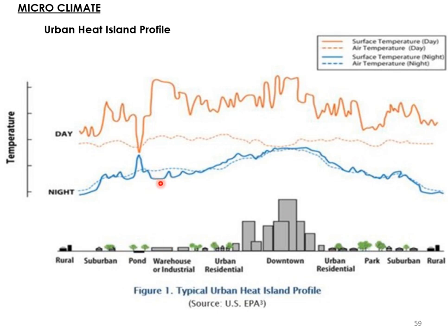Whereas the surface temperature will suddenly reduce here in a warehouse, because sometimes what happens in a warehouse, it's a very thin material. So the thin material can re-radiate faster. So that is why it is making the surface temperature a little lesser after your work hours. Like after the work is completed by 5 o'clock or 6 o'clock, and it's left very idle and nobody is there in warehouses or industrial areas, and suddenly it reduces the surface temperature, because the material is very thin. And even in rural areas, the material which is used is not concrete or brick walls, whereas they have used something like a thatched roof or an earth wall, etc. So that also can reduce the surface temperature.